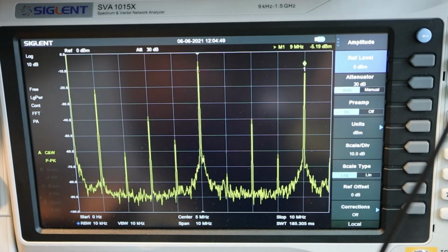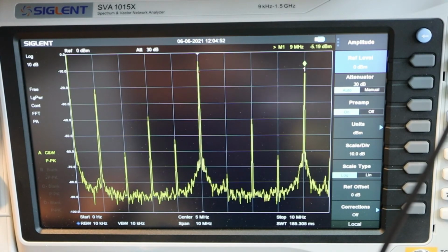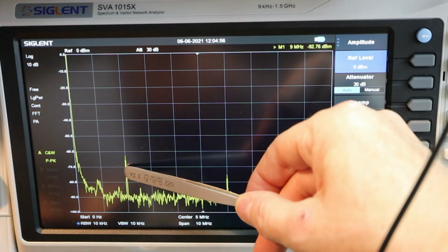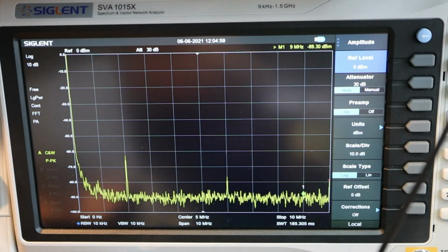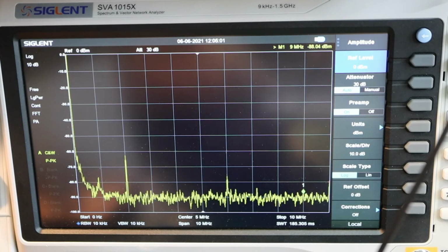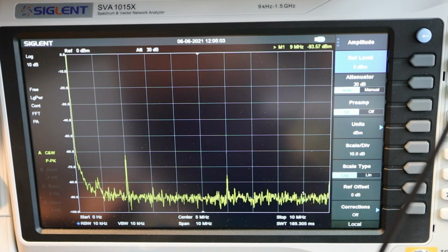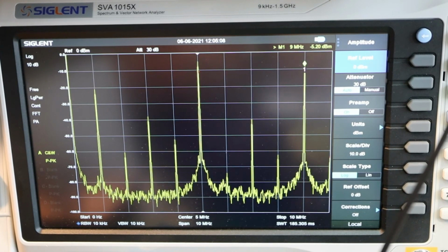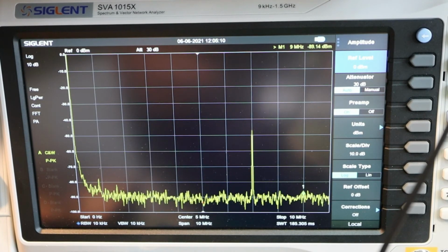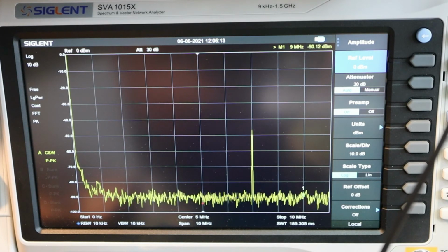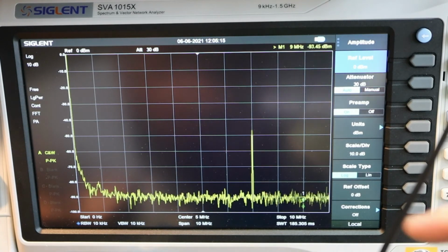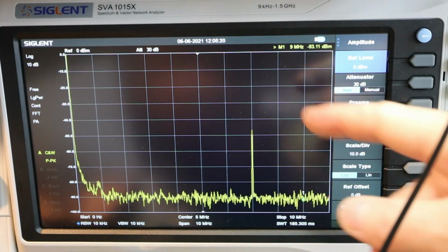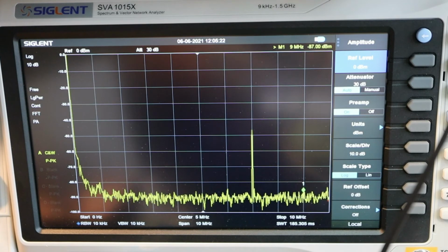If I just disconnect RF, you see a 2 megahertz LO pushing through all the way to the output. And there, you know, ideally this would be 0. And if I disconnect LO, then we have a 7 megahertz pushing through to the IF. But it's pretty much attenuated.